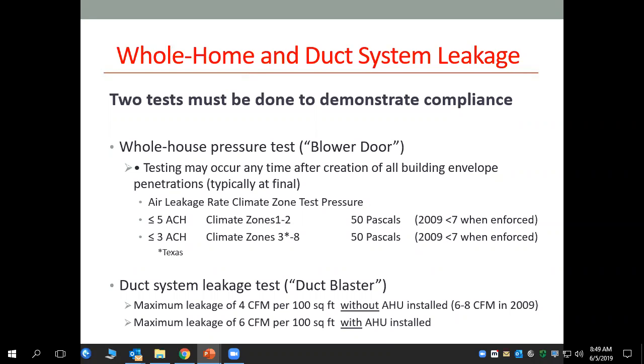And then the second form is the duct system leakage test, which, as a former HVAC contractor, begrudgingly we were dragged into using mastic because it added cost, but it actually helped reduce our CFM requirements in our HVAC systems. Then of course our tonnage. So it has been an effective way, not only when you change the house itself, but also when you seal up the ducts. It makes a huge difference on comfort and, of course, delivery of the air and the return of the air.